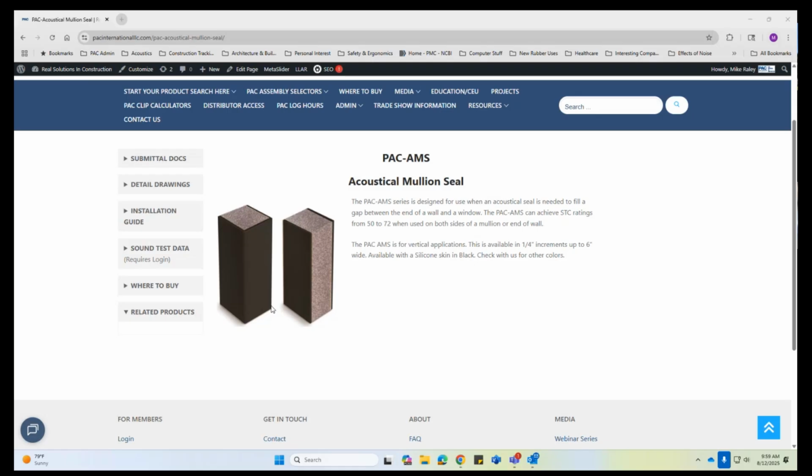So if you're primarily concerned about speech privacy, like between medical exam rooms, constrained layer damping can work well, and it might be all you need, plus some additional mass, making sure you seal and take care of all the details I just spent the last 45 minutes or so talking about. The constrained layer damping might be enough to get that transmission where you want it.